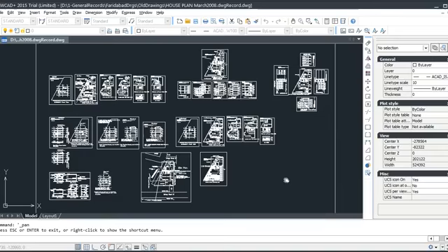And that proctor density must be 98% for structural backfill, for structural bases. It can be 95% for below ground, below floors you can say, and it can be maybe 92 or 90% for general areas where there's no load, or you can say some landscapes like that. So there are various ways to do it.